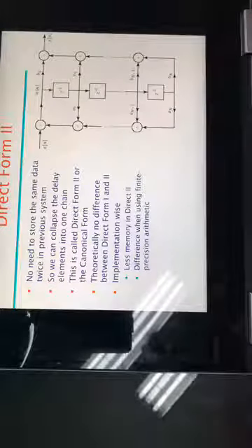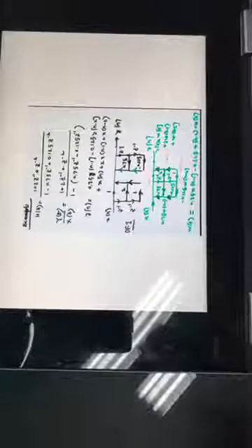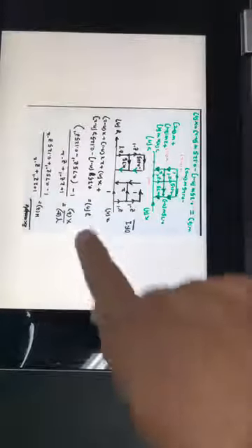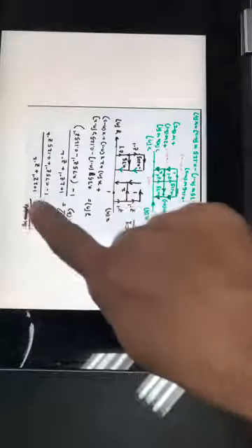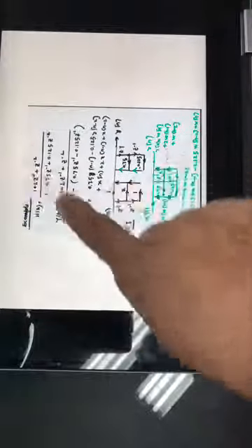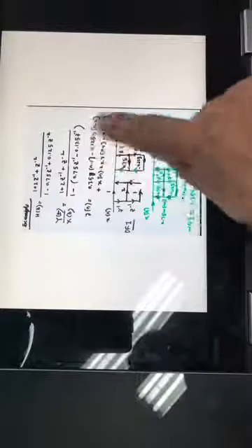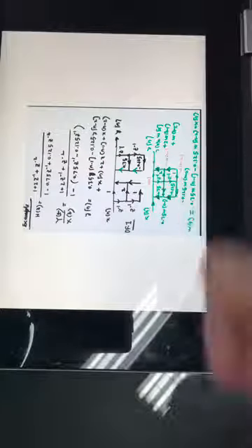And this is the example I have done. The same thing: I told you that if you're doing an example, put the transfer function in this form. You may not even need to write the difference equation. Just write this is b0, b1, b2, and with the negative sign and the bracket, this is a1 and a2, and just go and put these numbers there, and you're done with the question.